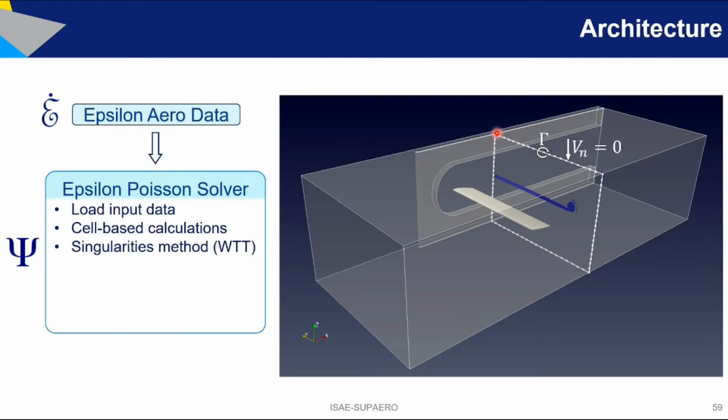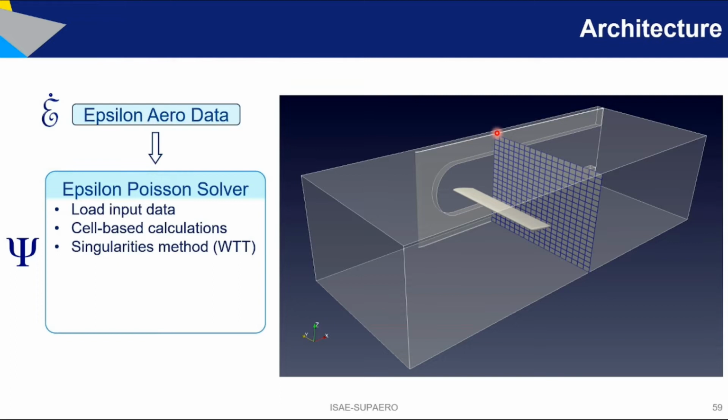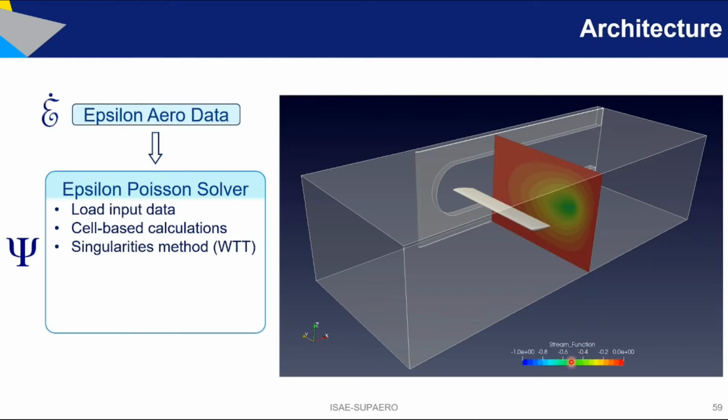So once we solve the linear matrix equation that gives me gamma, I generate a background grid all along the wind tunnel cross section, and at each point of this grid I compute the stream function based on the equation that I presented you before. Once I'm happy that the stream function actually follows the wall as expected, I can go to the next step, that's actually computing the stream function inside the wake.